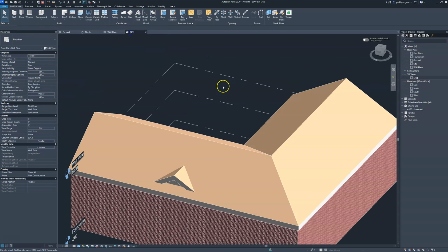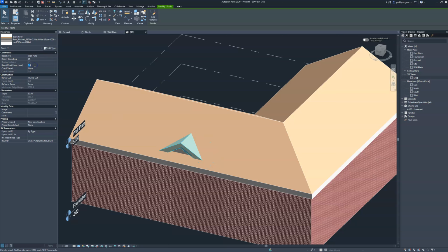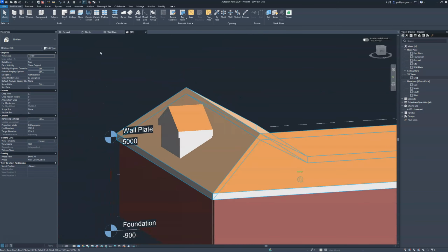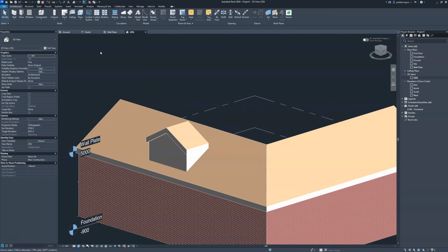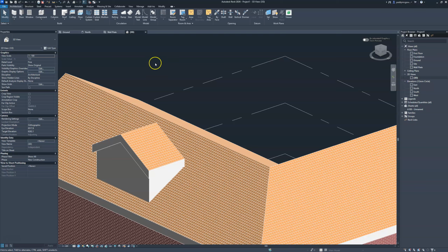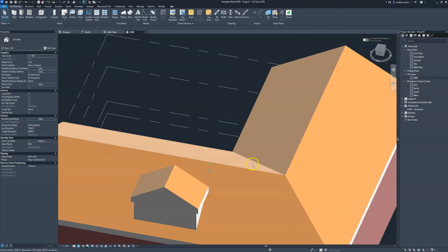So now if I go to my 3D view, you can see it's very low. So let's add an offset. Let's try 2 meters for now. Okay. I know it's very high and I can see that there is going to be an issue, but I just want to show you that before we do any joining. So let's try and join it now. We've got our walls in, we've got our dormer roof. We haven't done any trimming yet, and we have not done the opening. So we can see all these walls on the inside.